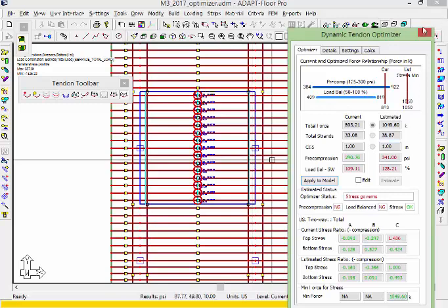The current stress now was the 893. The estimated stress now is 1050. So you can see that this is becoming an iterative process that we're using the recycler for. And the reason there's a difference between the previously selected application, which satisfied the isolated span, but it doesn't satisfy the FEM solution. So we have to go through that iteratively.